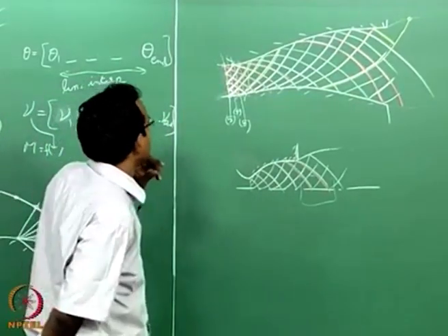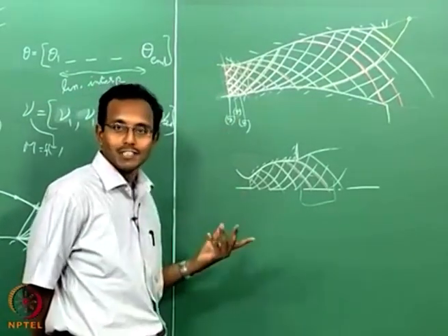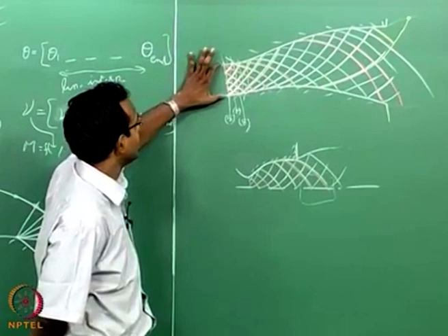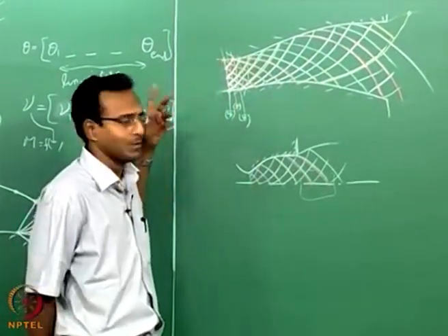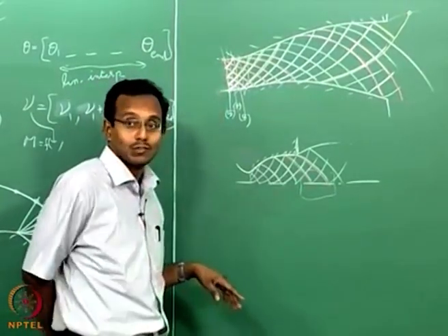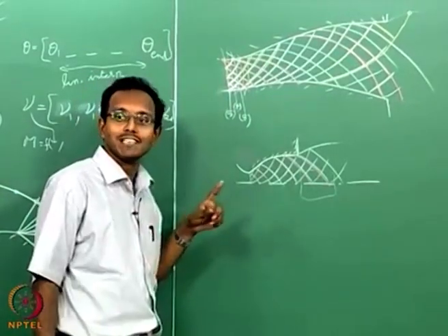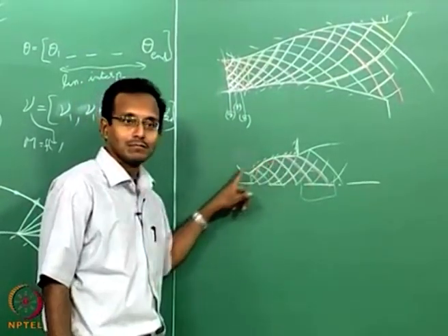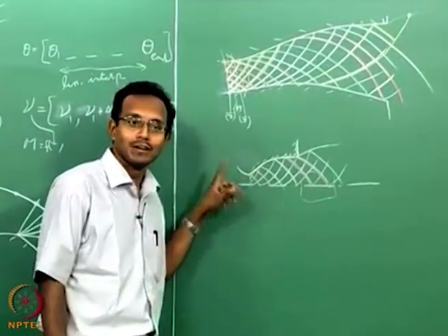Now in all this, we needed this initial set of data points. Of course, there will be problems where we will be given the initial flow condition and then we have to solve from there. That is simple, there is no more trouble there. I can just put however many points I feel like there. But there will be times when nobody knows what the data is. One such case happens in a nozzle throat. At the nozzle throat, we know it is somewhere there, M equal to 1.